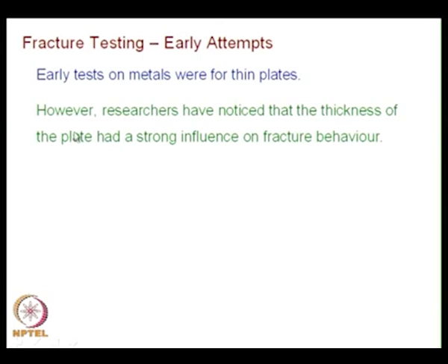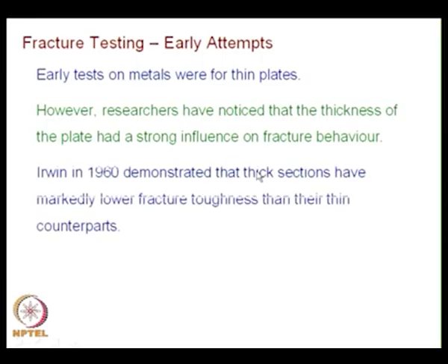However, researchers have noticed that the thickness of the plate had a strong influence on fracture behavior. In 1960, Irwin demonstrated that thick sections have markedly lower fracture toughness than their thin counterparts.